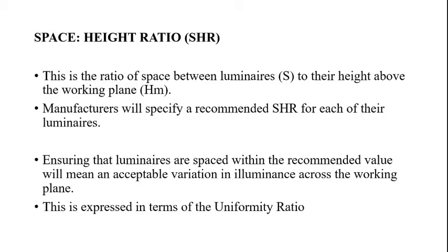Another important design factor is the space to height ratio. The desirable value of the space to height ratio will also be given by the manufacturer for that particular luminaire, so that the luminaire will give uniform illumination over the working plane.